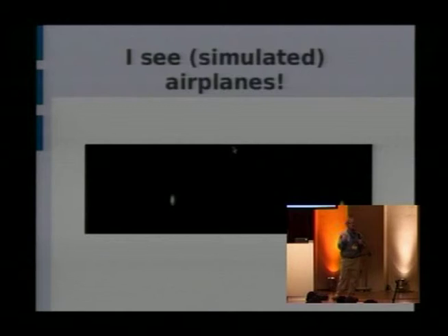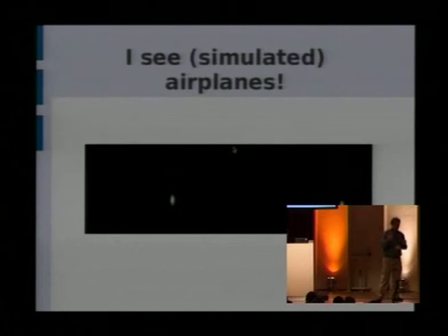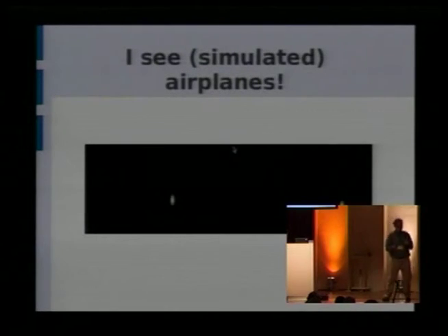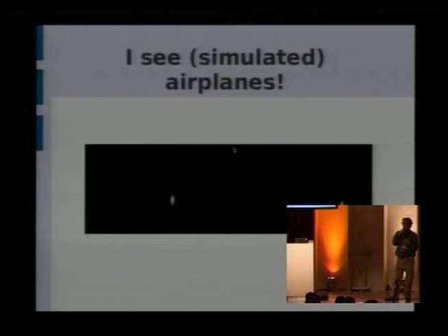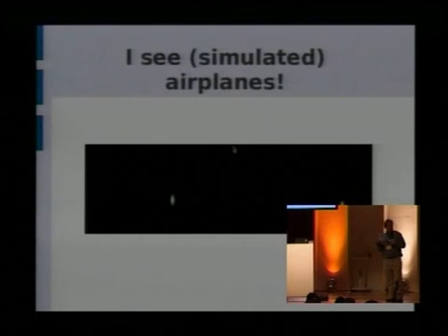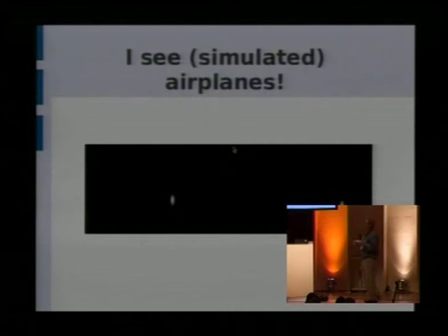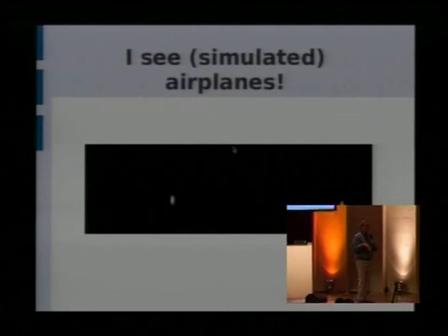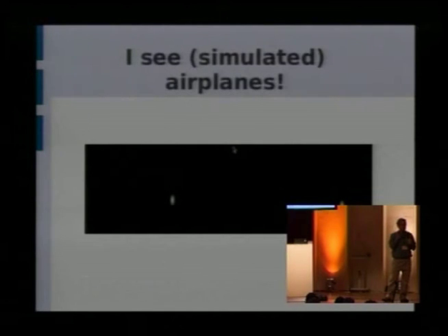If you start thinking about how, let me back up for just a second. So remember I was talking at the very beginning of the talk about how they had these radar systems where they sent out a pulse and then they stop transmitting and then they listen? Well, we don't control the transmitter, so it's on all the time. So the trick we get is that we can listen for a long time. And it turns out that the broadcast FM signal, particularly if it's tuned to something like very raucous rock and roll, has got really good properties for us. If they're just talking, it's not so good, seriously.